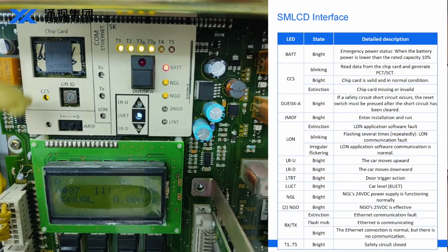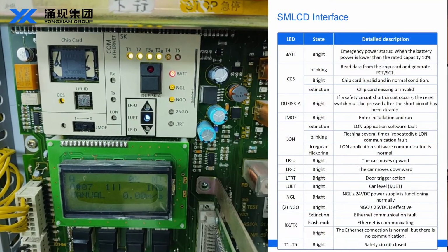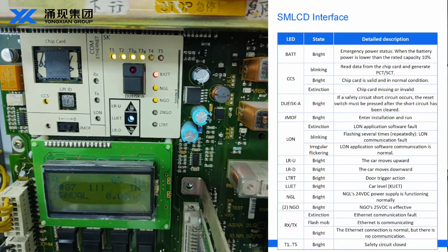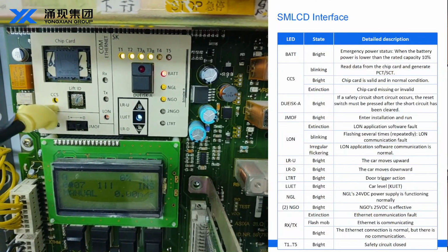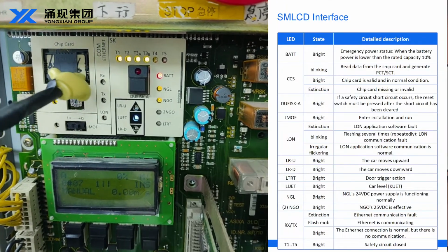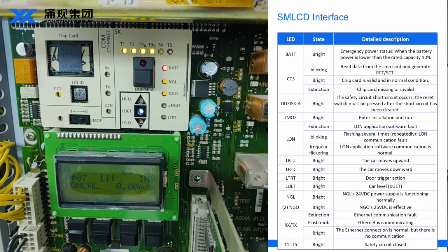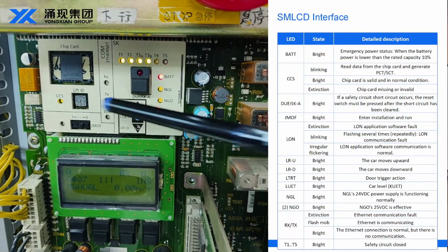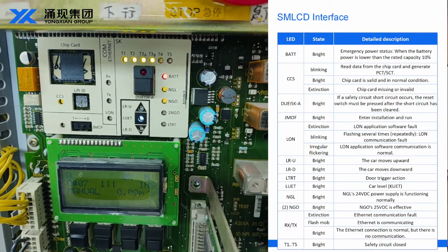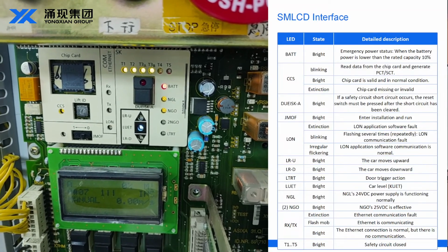So when an elevator is broken and we check the fault and find this light flashing, our first reaction is that either this card is broken or the main board is broken. If you find the CSS light is flashing, it means maybe the SIM card is broken or the main board is broken.